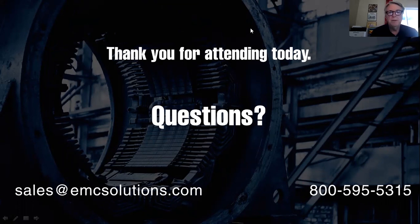By the way, let me mention one other thing. On the active filter, sometimes if the drive is off, there's a capacitor there, it generates leading vars, and sometimes people are concerned about having too many leading vars on the system. This is generally pretty easy to correct by simply specifying a capacitor cutout contactor on your passive filter. And what that does is keep the capacitor in the filter off when the drive is off.